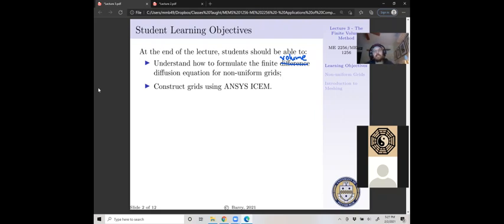It's just incredibly hard. Oftentimes you don't want a uniform grid, especially when we start talking about flow problems, because you want a high density mesh in regions where you're going to expect your boundary layer to form, depart from the surface, eddies and vortices to form. But in your free stream, you really don't care about much. So you've probably seen a lot of situations where we don't have uniform grids. And we're going to talk about how to implement that.